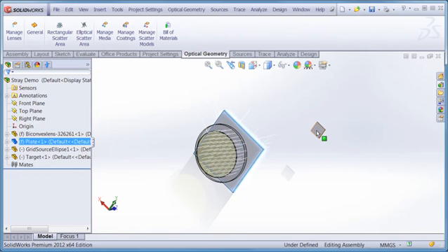Apex will adjust the ray distributions so that all of the light gets scattered towards my target, but it will adjust the energy in those rays to reflect the amount of energy that would enter that angular region as defined by the scatter model and the geometry of the system.